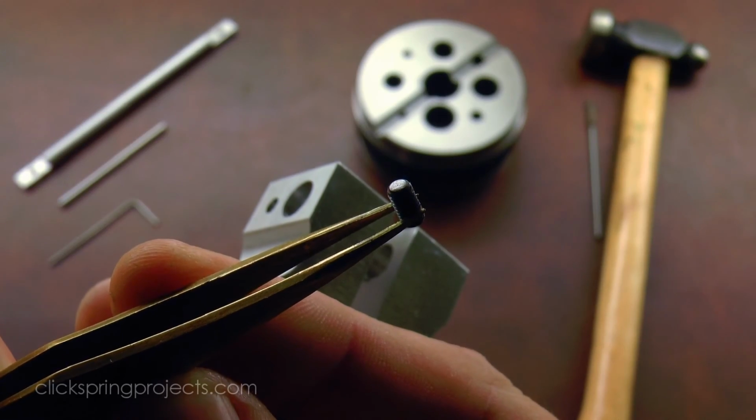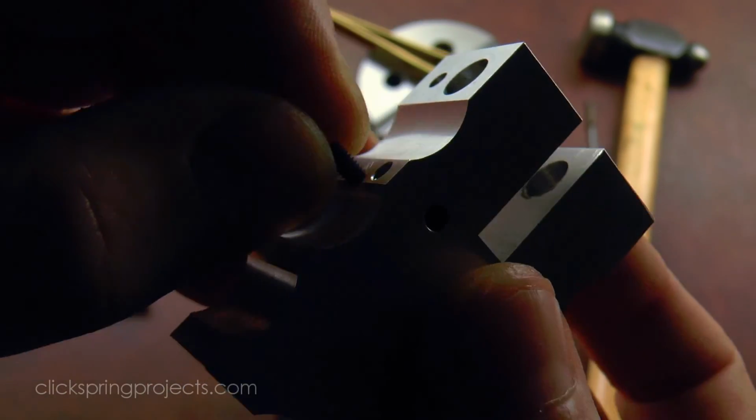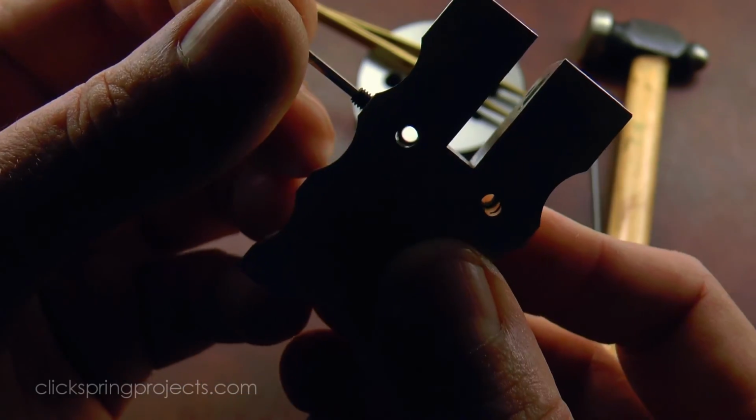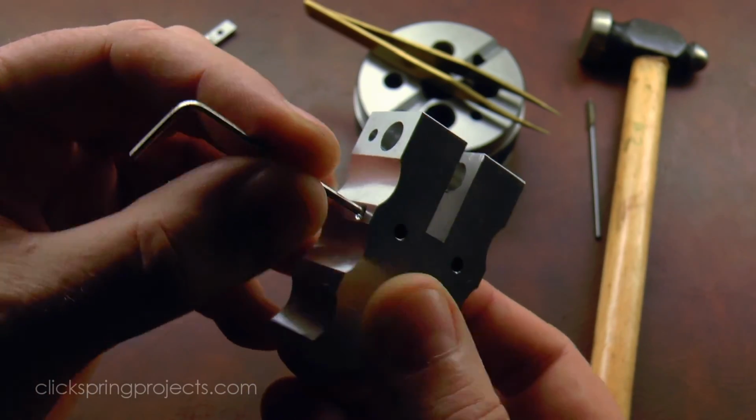And just as a quick aside, I've rounded off the ends of the grub screws to minimise their capacity to bruise the button cutter shanks while they're still in their annealed state. Just a quick touch on an abrasive belt or stone and they're done.